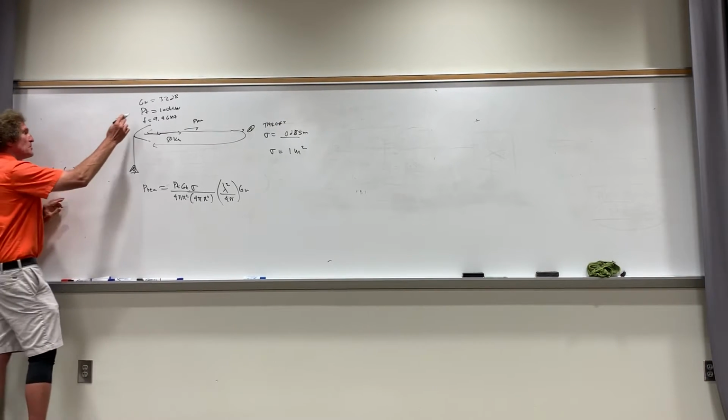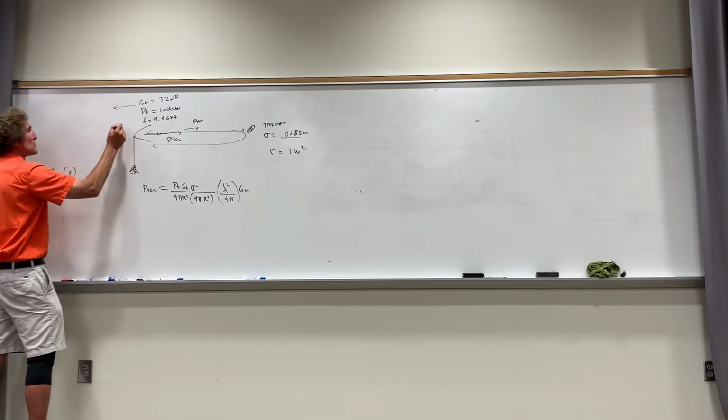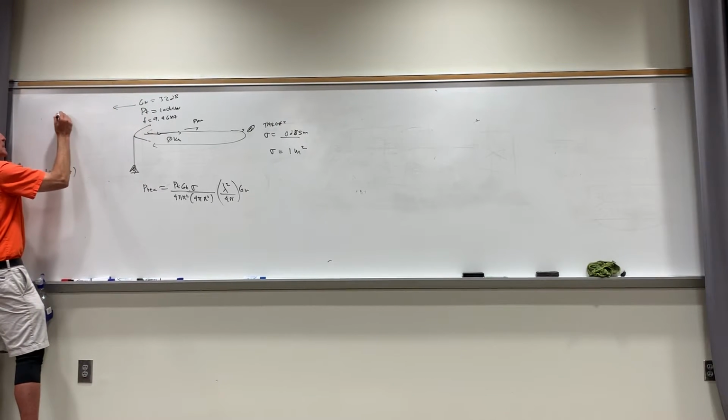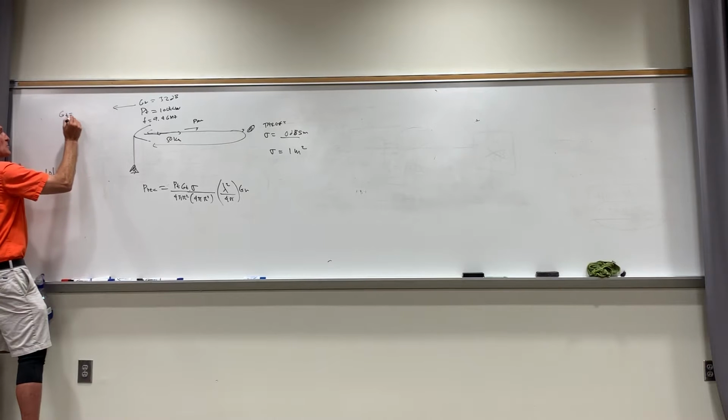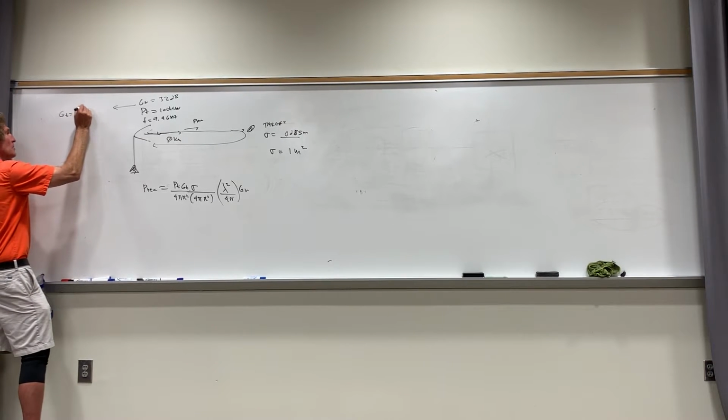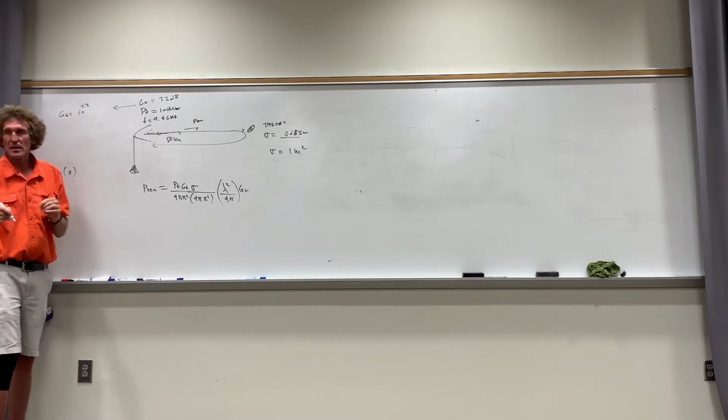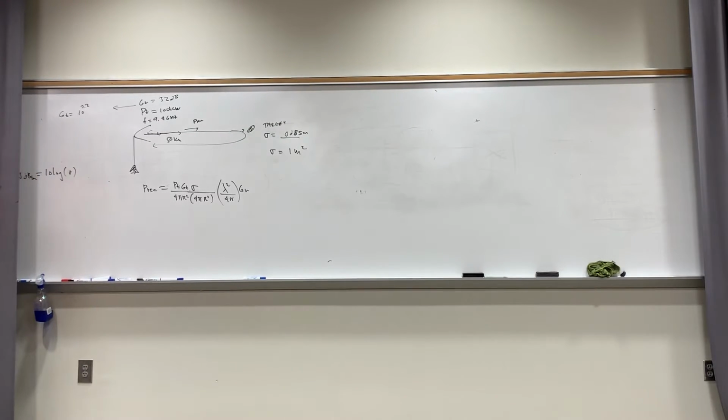But we have 32 dB, that's the logarithmic gain. The actual gain of the transmitter would be what? 10 to the 3.2, wouldn't it? Because you would divide that 32 by 10, and then you would take 10 to that power, whatever is the remainder. Are you all with me on this?